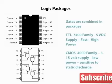Circuits using CMOS need to take this into account. Good ESD practices when handling chips is necessary. The main family name for CMOS is the 4000 series. The quad 2-input AND gate to the left is a 4081 package in CMOS.